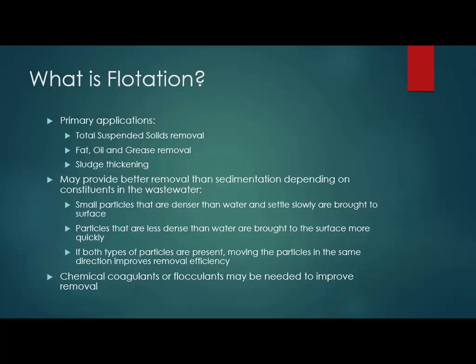In some cases, flotation may provide better removal of particles than sedimentation, depending on the constituents in the wastewater. If you have very tiny particles that may settle slowly, the flotation process could be used to bring those to the surface where they could be skimmed off more quickly than they would otherwise. If you have particles that are actually less dense than water, such as oil, those will over time come to the surface, but the flotation process can be used to enhance that and reduce the retention time that's required.